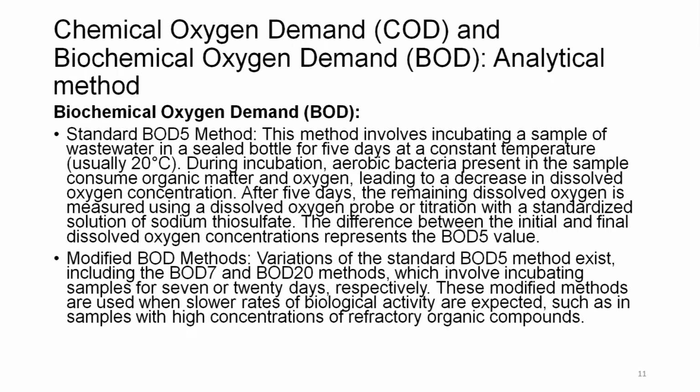Biochemical oxygen demand, how is it analyzed in the laboratory? Standard BOD5 method. This method involves incubating a sample of wastewater in a sealed bottle for 5 days at a constant temperature, usually 20 degrees centigrade. During incubation, aerobic bacteria present in the sample consume organic matter and oxygen, leading to a decrease in dissolved oxygen